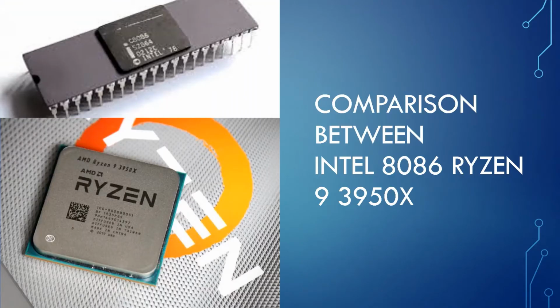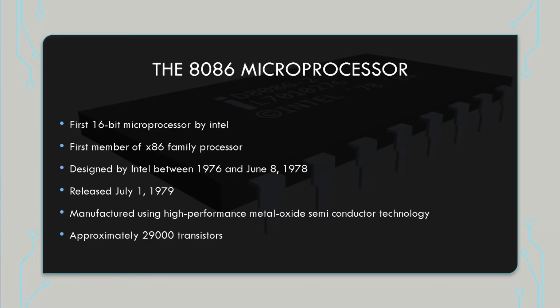Hello everybody, for my part, I will talk about a comparison between our selected processor and the 8086 microprocessor. Before we get started, I will show you the background of the 8086 microprocessor. The 8086 microprocessor is the enhanced version of the 8085 microprocessor. It is an integrated circuit with all the functions of a CPU, however, it cannot be used standalone since, unlike a microcontroller, it has no memory or peripherals. The microprocessor does not have RAM or ROM inside it.